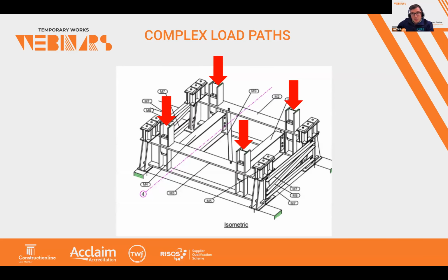To show that visually, vertical forces are applied something like this. The moment is applied something like this. This is obviously very much on a 90-degree angle. We've got to consider, if it's a symmetrical base, we might be considering 0 and 45-degree scenarios. For a grillage, though, typically we consider every 5-degree increment to make sure that we're modeling the worst case scenario for the grillage, which is obviously a hell of a lot of load cases. We've also got the horizontal forces and the torque forces.